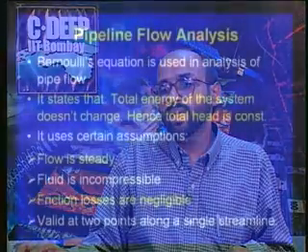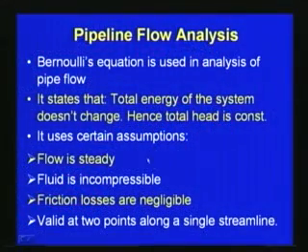So here Bernoulli's equation is applied by using certain assumptions. The assumptions used here are: flow is steady, fluid is incompressible, friction losses are negligible, and valid at two points along a single streamline. So with respect to these assumptions we use Bernoulli's equation and solve for the problem.